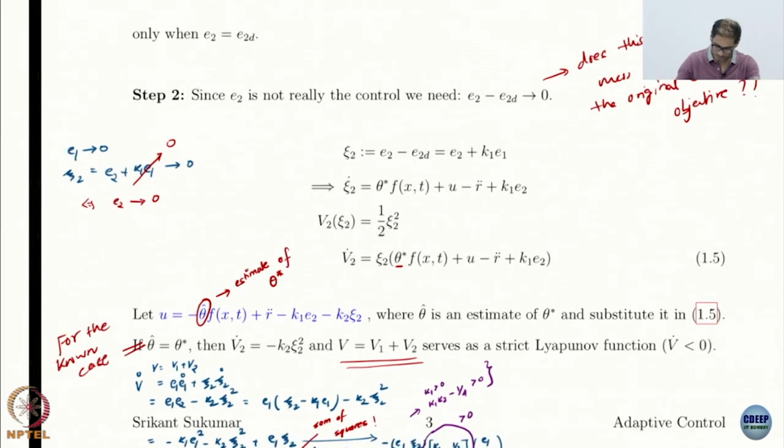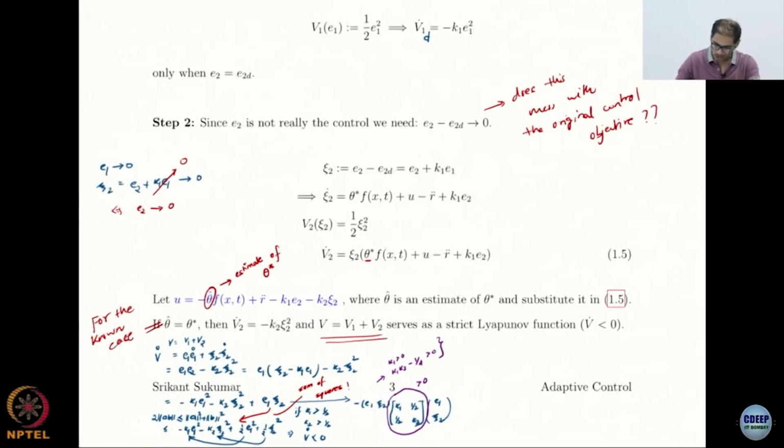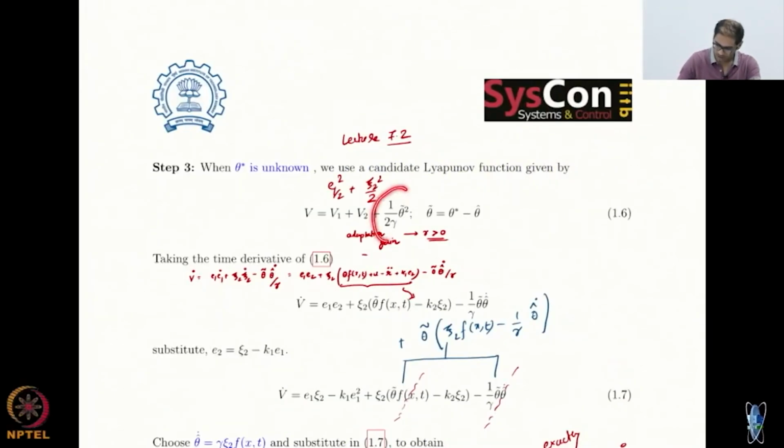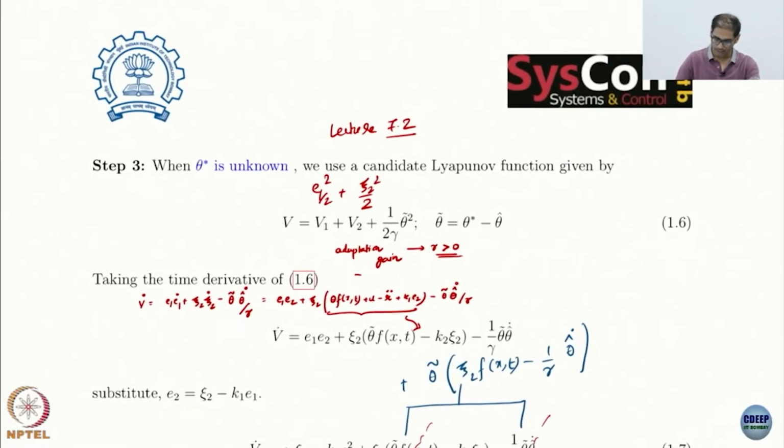And once you do that, you add to your Lyapunov function a term in the parameter error, right. So you had this Lyapunov function for the system, or the control Lyapunov function. Remember that we need a control Lyapunov function or a strict Lyapunov function, right. So you should not even start doing adaptive control without a CLF or a strict Lyapunov function.